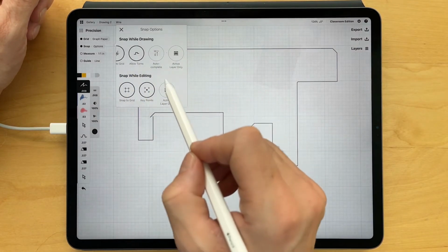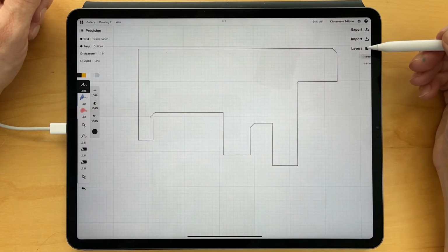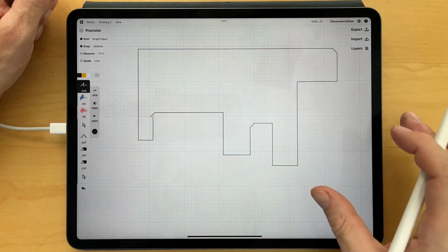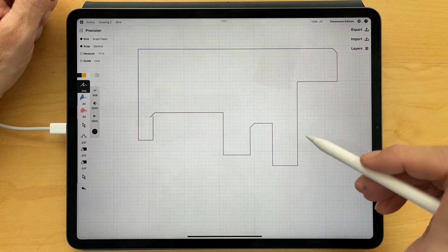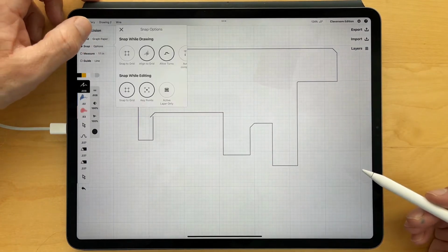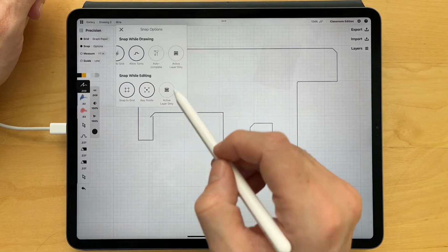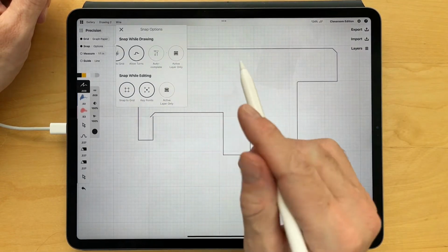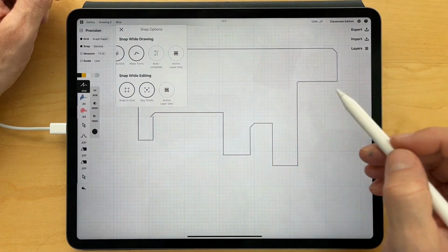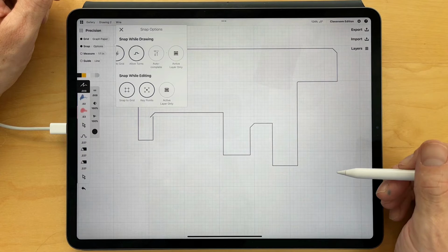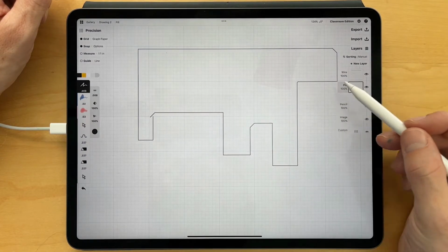Active layer, what this also means for drawing and snapping. Currently, I have one layer I'm drawing on. If there are other elements on different layers, I can snap to those objects on the different layers. But most times I have this actually turned off, so I can snap more freely. Or if I only want to snap something on this layer, then you turn this on. Okay, good. So let me maybe quickly give you a demo what this means.